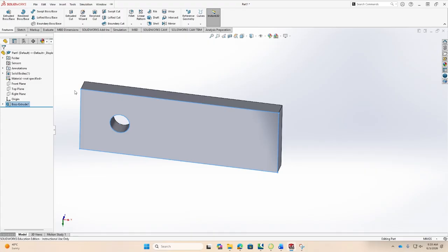So normally for initial design, we definitely don't need to go into that level of detail. What I will use is, I will later apply certain constraints on this hole directly to mimic the behavior of the pin, okay? And again, with the assumption that my pin failure is already fully defined based on the simple shear criteria that I have used. So with that assumption, we will analyze the bar purely.